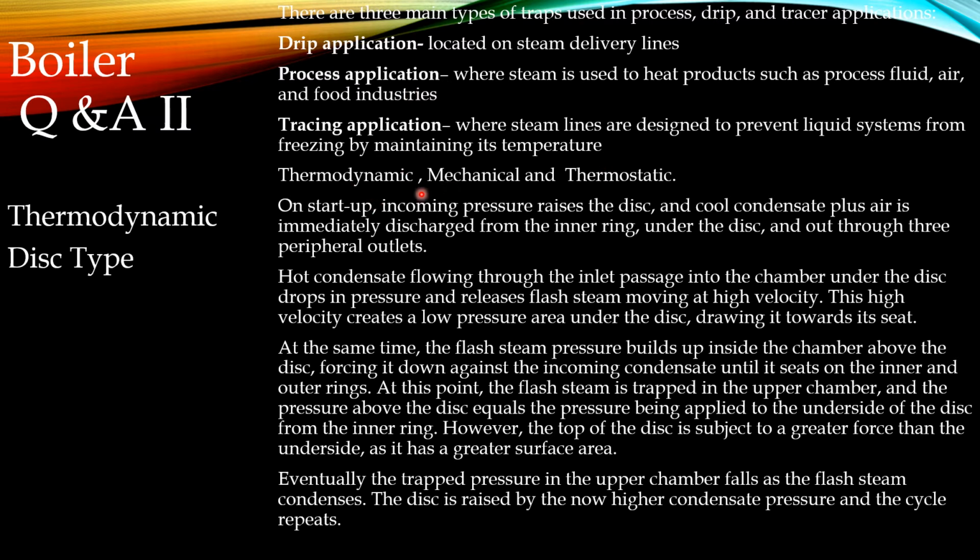And the three types of traps are thermodynamic type, mechanical type, and thermostatic type. In this episode, we will see about thermodynamic type. Thermodynamic disk type. On startup, incoming pressure raises the disk and cool condensate plus air is immediately discharged from the inner ring under the disk and out through three peripheral outlets.